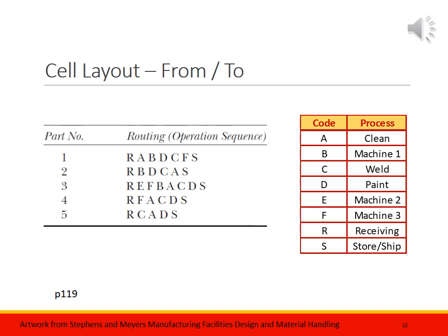All right, and you can see here, it's sort of what we saw in the previous slide, where in the X-axis you have the routing, A, B, C, going across. And on the Y-axis, you have it by part number, sort of the part number domain. So you have process routing in the part number domain. That's actually how you'd say that. What's interesting to note in this example is that things aren't running quite as smoothly as they were in the previous example because we have what's called routing reversals.